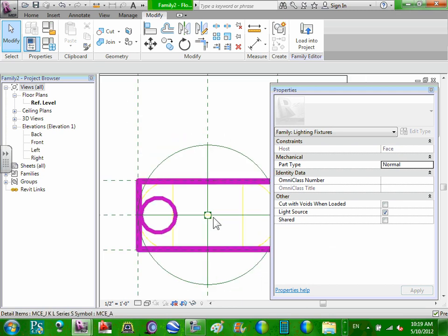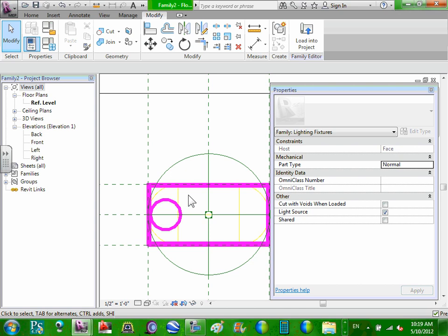If we had a box here or whatever, I'd bring that symbol in, I'd put its legs on this line so that it's sitting at the midpoint of that box, because the middle of the junction box is 18 inches off the finished floor or whatever. So that's where you got to think about where you want that symbol to be. Okay.